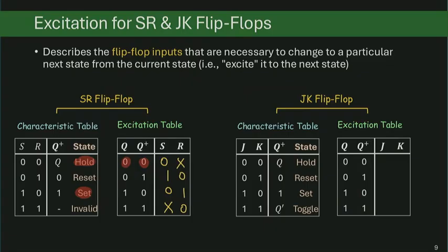All right. And then I'll give you 2 minutes to work out the excitation table for the JK flip-flop by yourself. Again, based on the characteristic table, see what operations allow you to make a transition happen, and then try to represent the JK condition in the most compact way, with as many don't cares as possible. The 2-minute timer starts now.